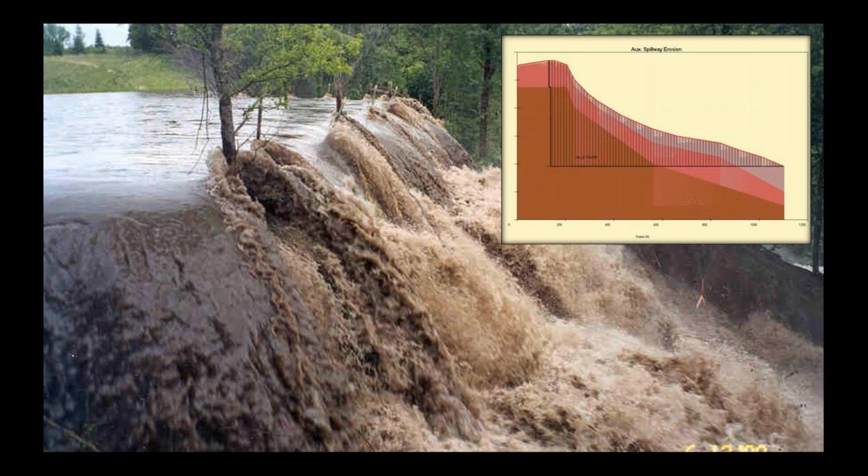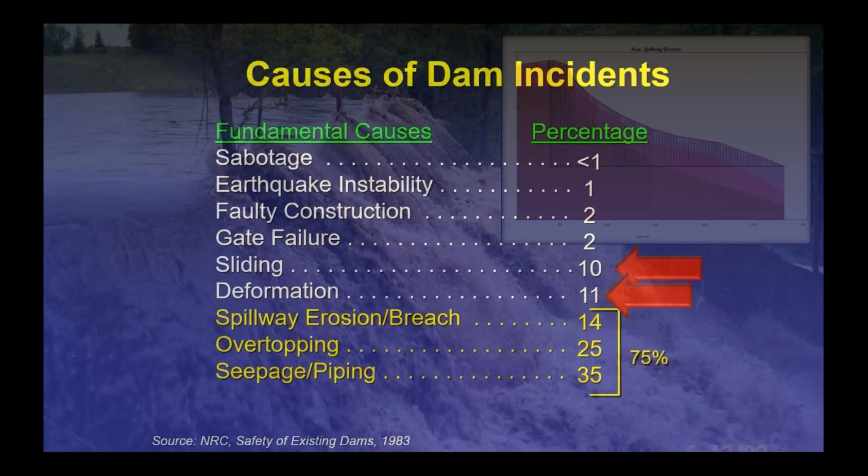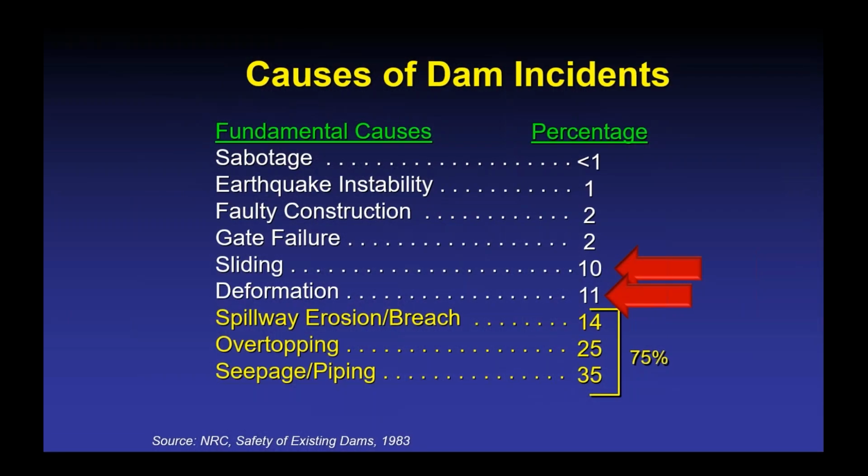If we were doing an analysis of this using the SITE software, which was developed by the NRCS to evaluate this type of spillway, we're essentially starting with the failure advanced at this location, and it's just a matter of head cutting upstream. So look for those kinds of inadvertent modifications to a spillway.